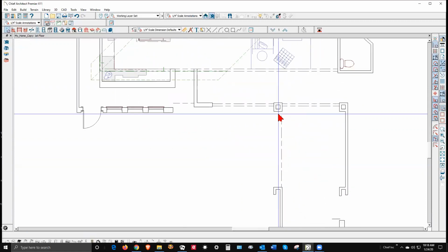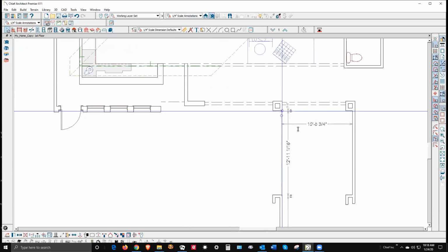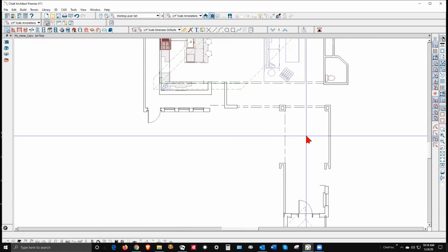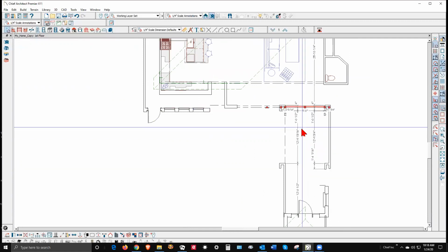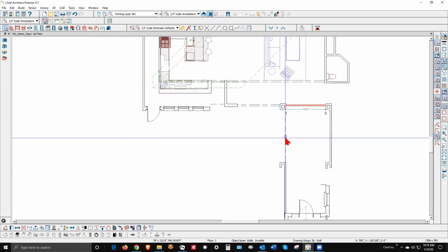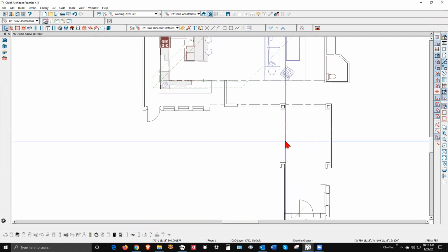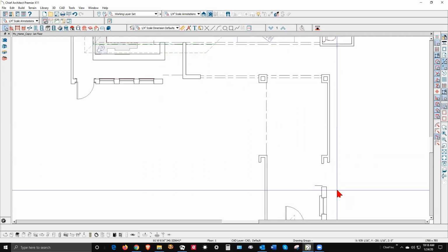Like this is probably this wall here, this room divider wall isn't closed. Let me close that. See if we get it done. There's something else wrong. Let me just click, make sure all the walls are connected. I'm just clicking on a wall and then hit this little tool here that's connect walls. Oh, here's the problem right here.